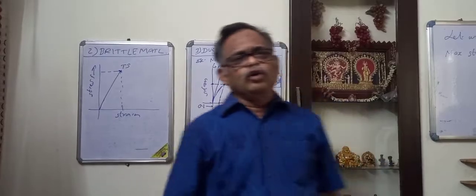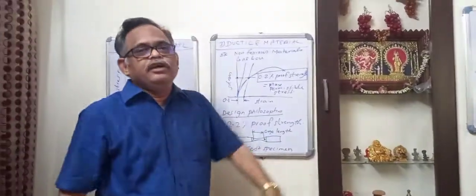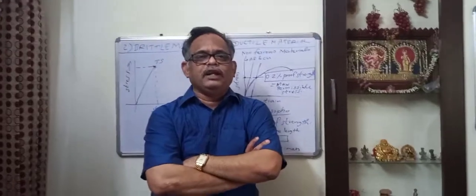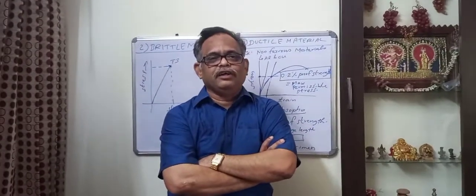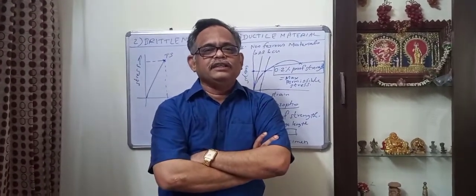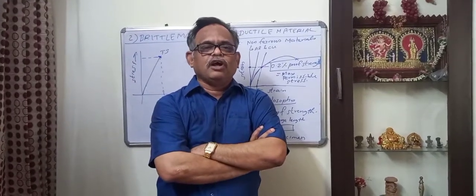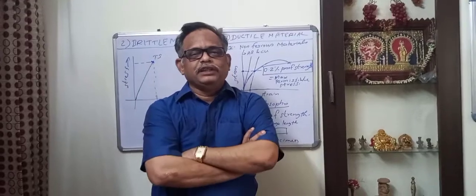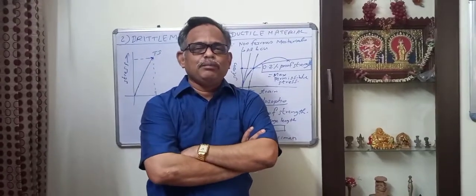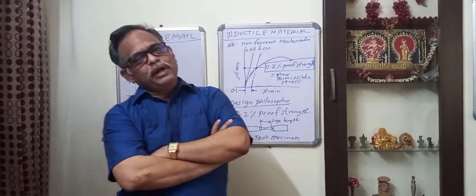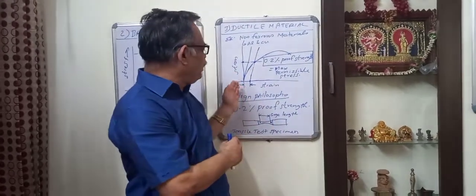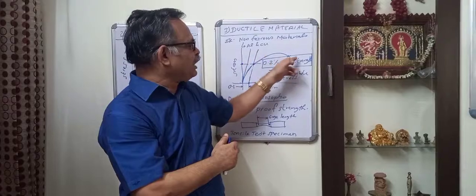And I also want to explain one more thing. In boiler pressure part design, the pressure parts are always at a very high temperature. When temperature increases, the material loses its stiffness and the behavior of the material becomes like this.